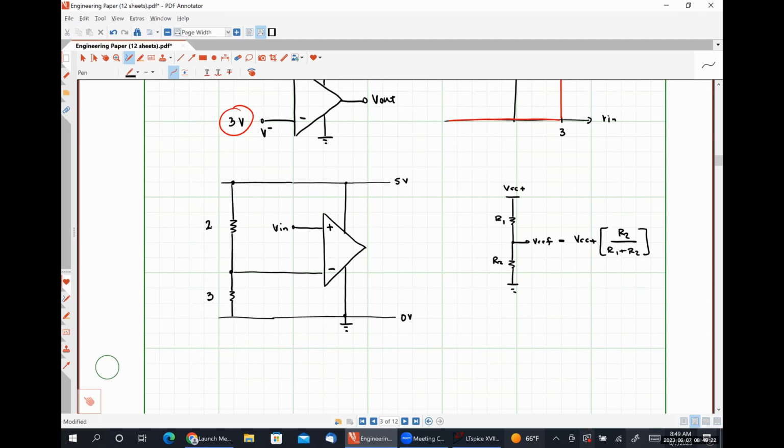And similarly, since our input resistance is on the order of mega ohms, we want our biasing resistance to be much smaller than that input resistance. So generally speaking, the sweet spot for biasing an op amp is to use kilo-ohm size resistors, because they're about 1,000 times larger than the output resistance, while being about 1,000 times smaller than the input resistance.